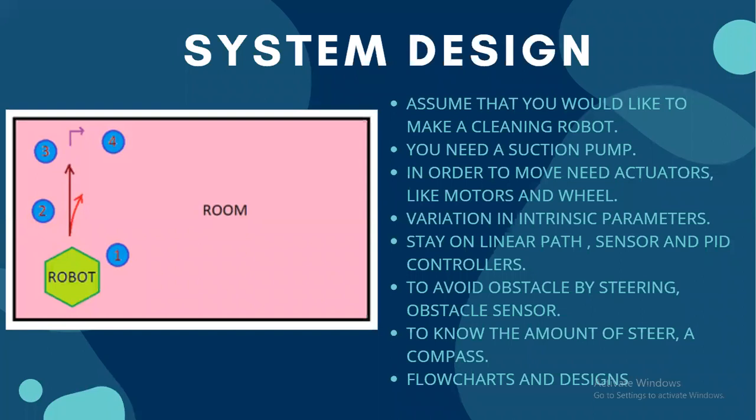Different motors are going to extract different currents, and so they will have different RPMs, rotations per minute, and the robot will take a turn. In that case, you need to apply another controller, maybe a PID or a fractional PID. Definitely, you can use a PID controller, right?